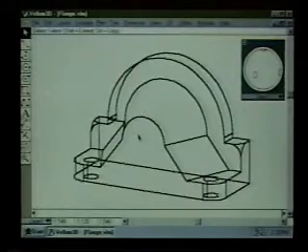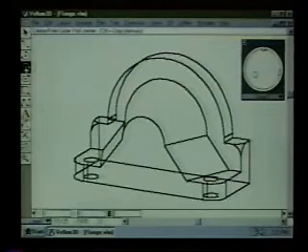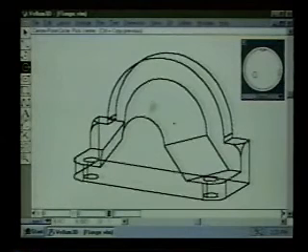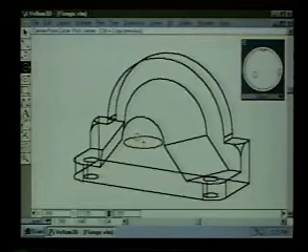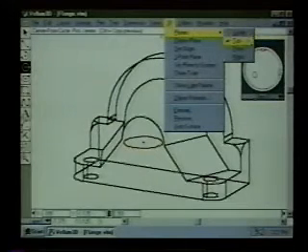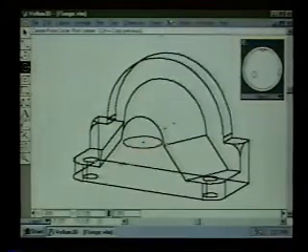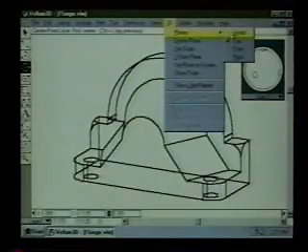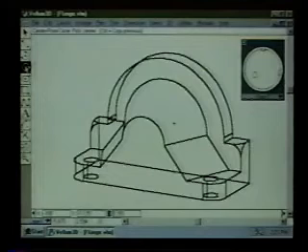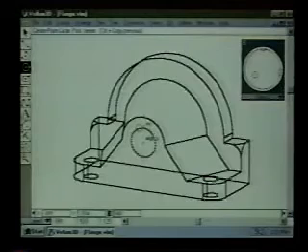The next thing I'd like to do is put kind of a tapered slot in the front of this part. And so now we can see how Vellum handles working in 3D as far as the different work planes. If I pick my circle tool, touch the circle to wake up its center, and draw a circle, it initially goes parallel to the top and bottom face because my current work plane is set to top. Well, if I want to draw on the front of this part, it makes sense that I ought to change my plane to front. And sure enough, it's like putting a sheet of glass on the front of the part, and when I touch this and go here, now I can draw circles right on that front.